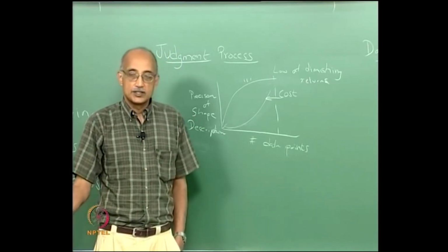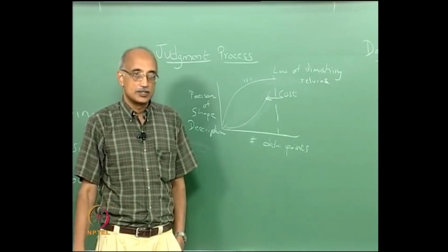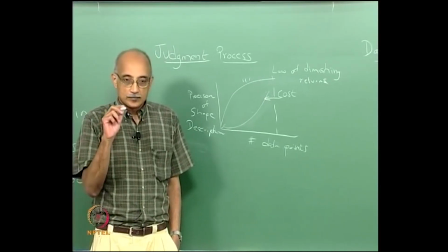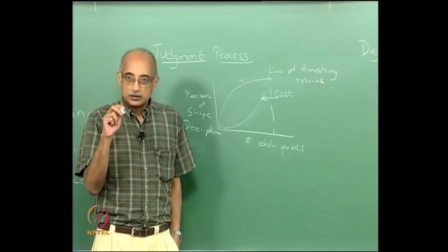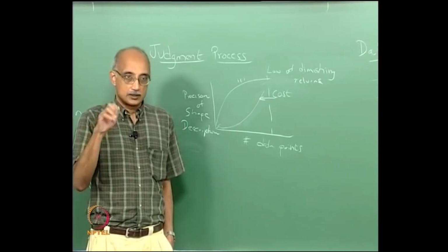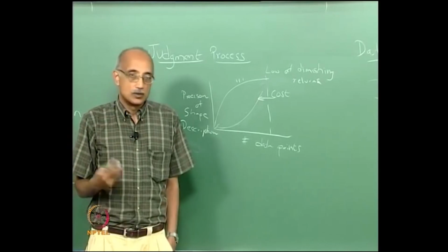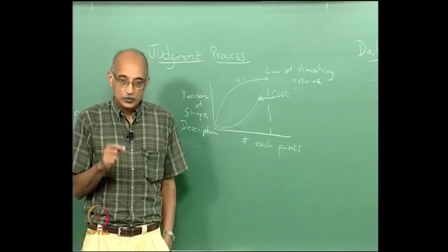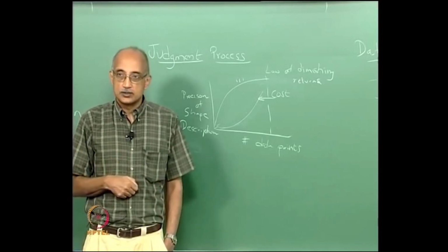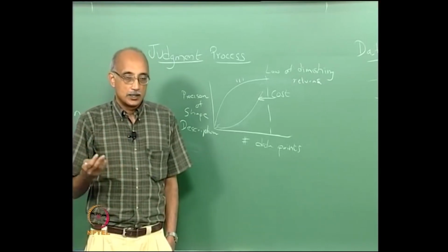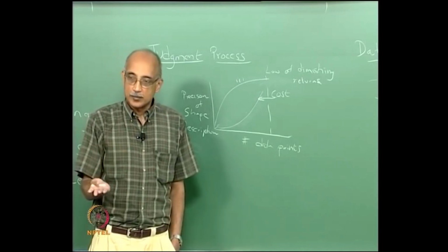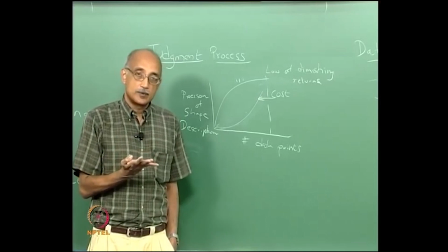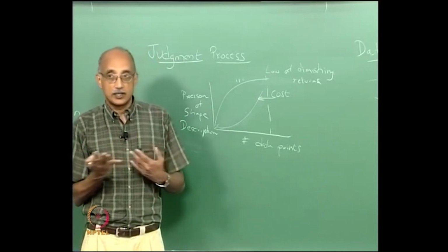So a hard drive fails in the field and the field engineer brings it back for failure analysis, and the indications are there is a particle that is stuck on the disk at a particular location. So you do your FA, you bring it into the lab and you carefully remove that particle from the disk using a tape or whatever, put it on a slide, put it under a microscope, and you want to look at it to assess its shape, because the shape of the particle can tell you a lot about where it came from.